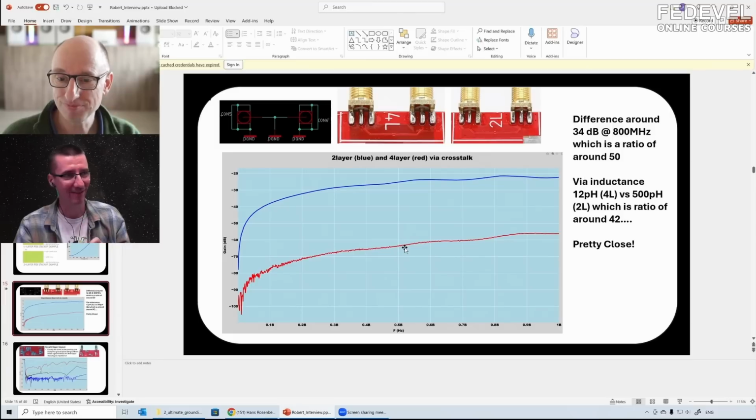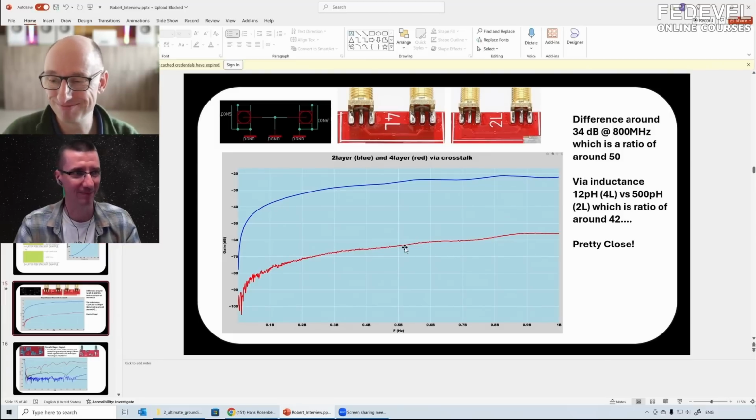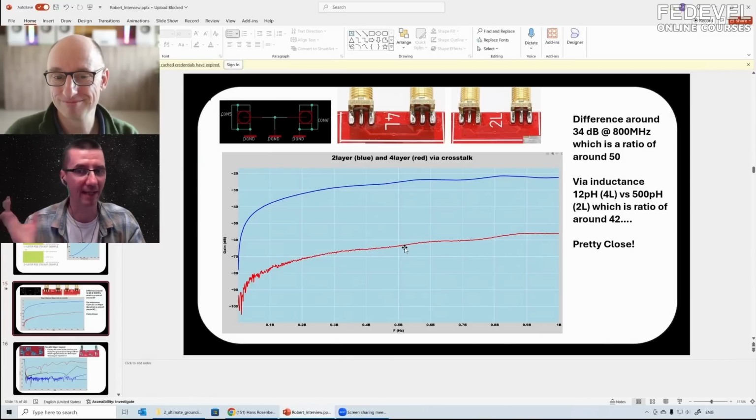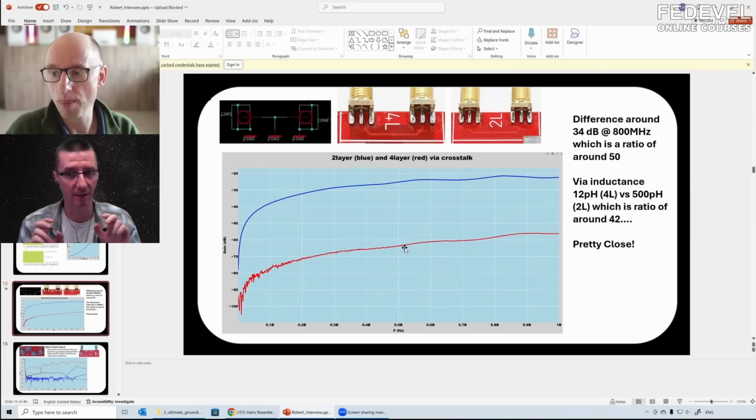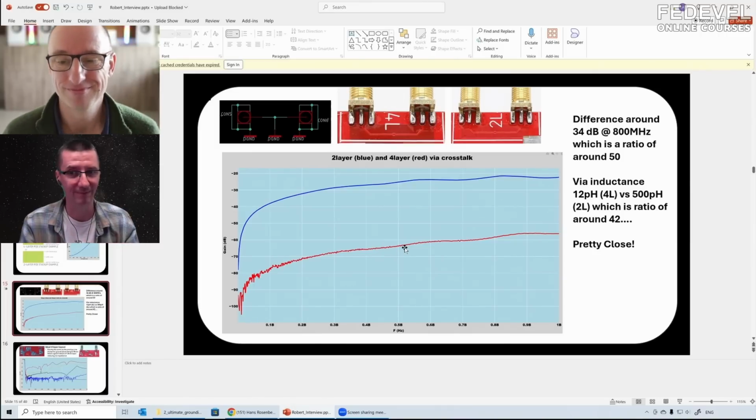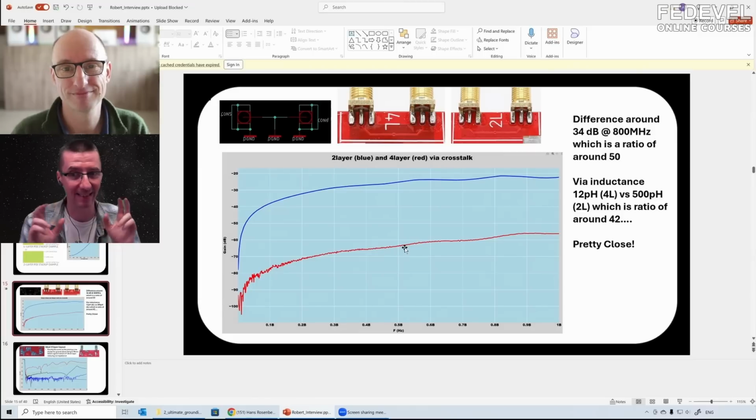I would like to clarify. So basically, yes. What this connection has here, for DC, it will show nothing, because there is a short circuit. But for higher frequencies, they will actually go through, even though the trace is grounded. It's not really grounded because there is an inductor. There is no direct short circuit, there is an inductor.